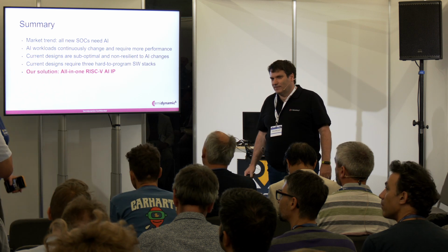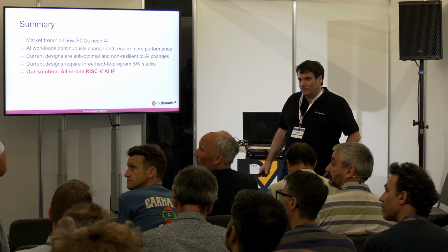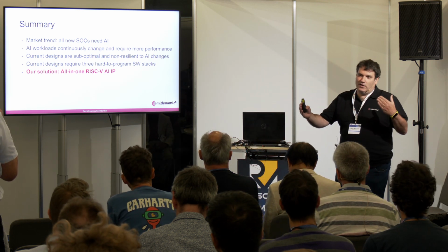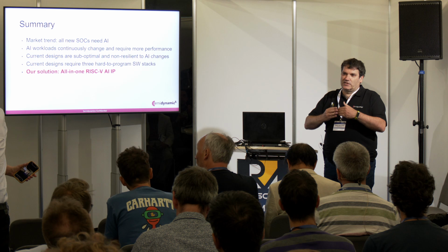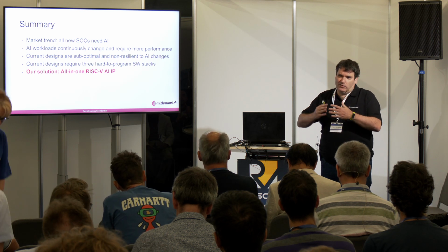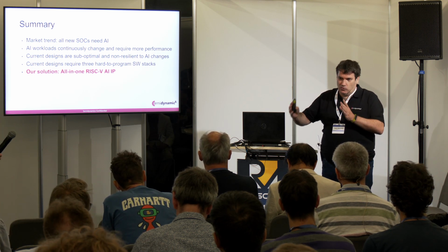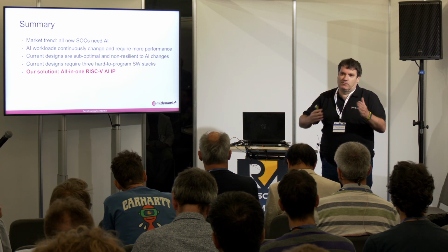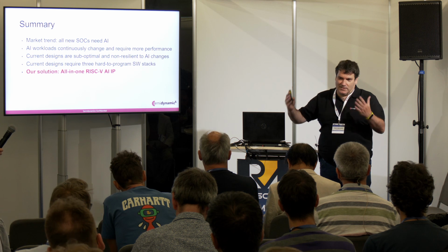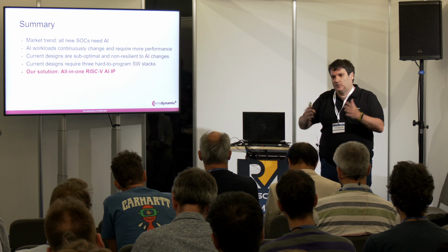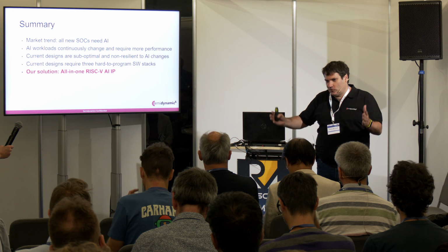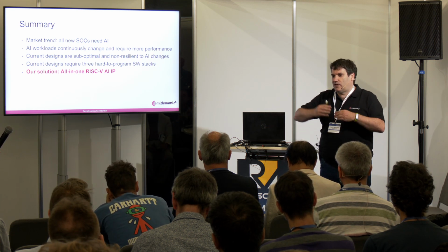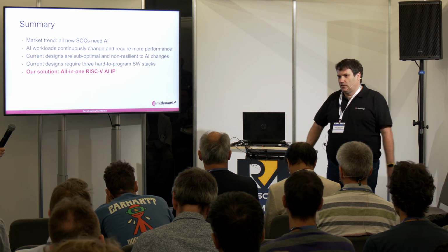Thanks. Hello. Is Gazillion misses a kind of transfer predictor? No, it's a way of having multiple outstanding misses. The current cores handle around 16 to 20, or 25 outstanding misses. We are able to have up to 128. You need special logic, because the usual way to do it is CAM matching and so on, and you cannot afford that for 128. So that's our secret sauce. We are able to manage up to 128 random cache lines, with secondary misses and so on. That's the thing that we are doing.